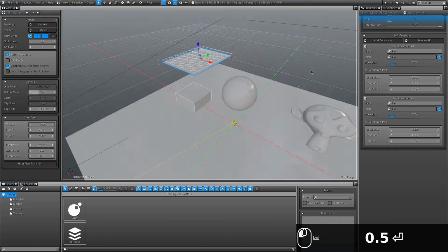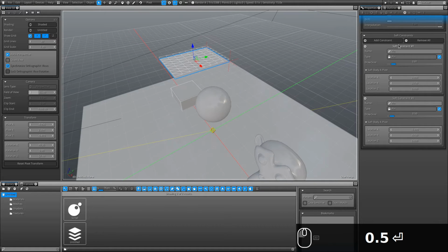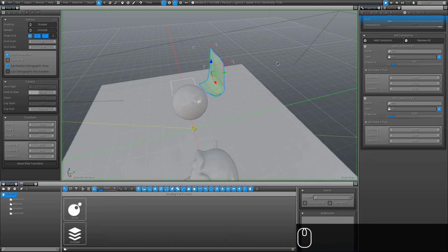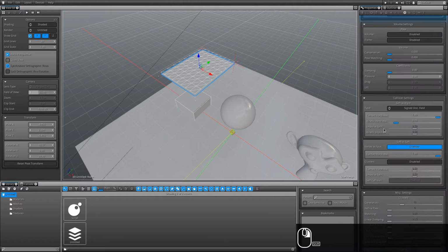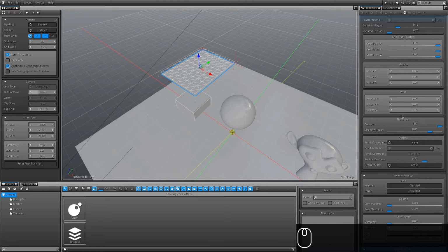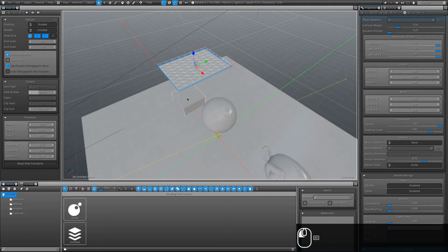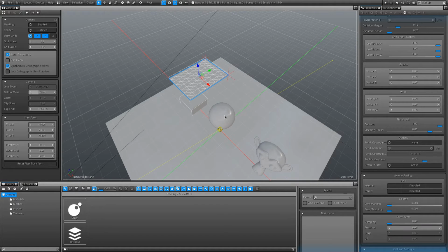And another thing that we probably want to do to make it more vivid, we want to have some wind that will be applied on that cloth. Instead, it's simply going to deactivate like this, which doesn't give us a very realistic effect. So, of course, we could use here the wind direction velocity vector of the Softbody, but I found it more convenient to actually add an energy field of the type wind.